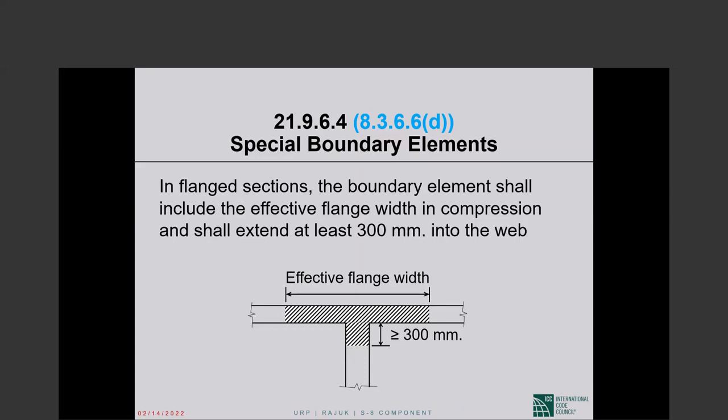Again, something that has been discussed before. If we place a shear wall in the first two floors of a 5-storied building and this continues to the other top floors, does it lead to irregularity? You have to figure that out by the criteria we discussed, the tables of vertical irregularities. So check them, and if you do fall under them, yes. If no, then no.